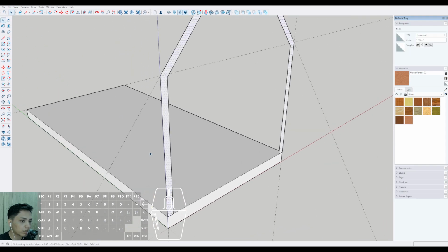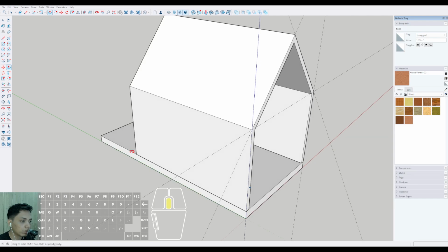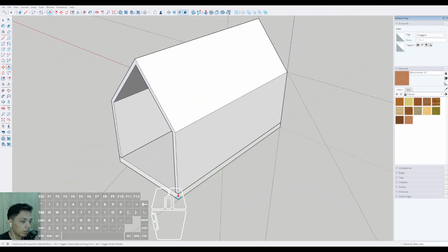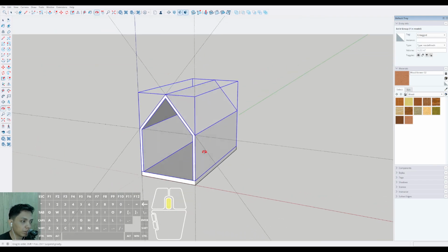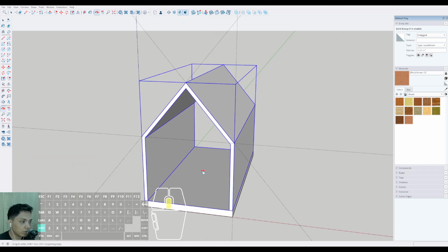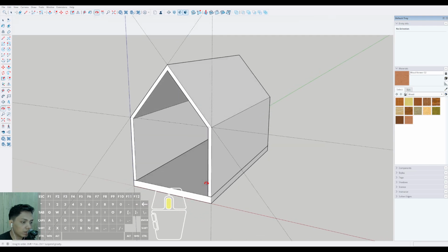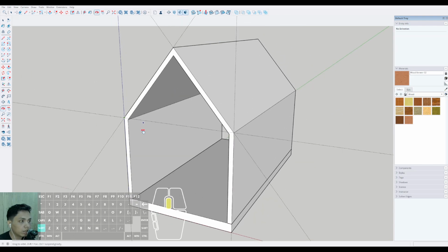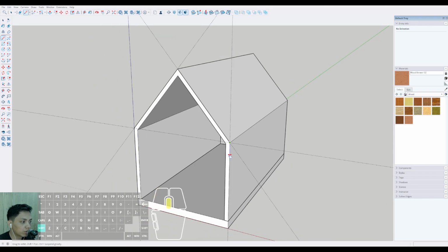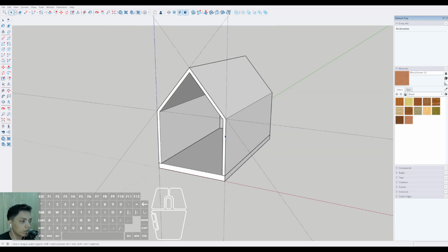Then we can click this plane, click the push tool. Then we can drag to the back and click in this position. Okay, so we can triple click, right click, and also make group, and we can get the basic shape of the Scandinavian house. Then we can also add more elements on the front of the Scandinavian house by clicking this line, and then click this point, then click this point. Just follow my steps, and then close this point, and then press space to neutralize it.